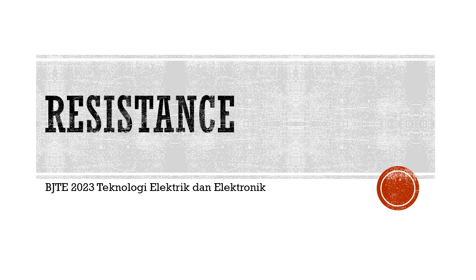Today we will look at a new chapter titled Resistance. Resistance is opposition to the flow of current. Some materials such as glass and rubber offer great opposition to current flow. Other materials such as silver and copper offer little opposition to current flow. This chapter examines the characteristics of resistance, types of resistance, and the effects of connecting resistors together by a conductor to form a circuit.